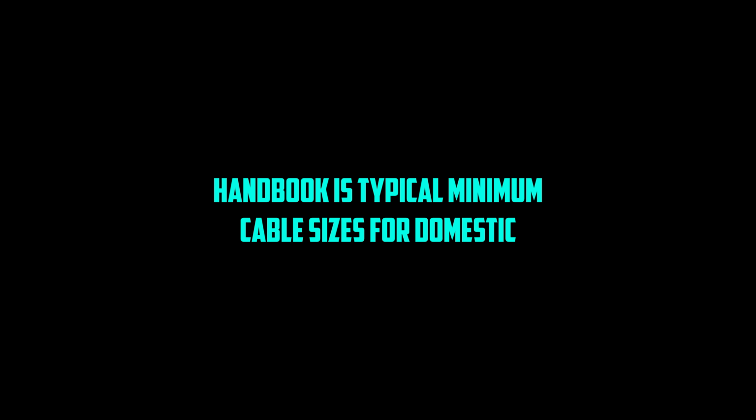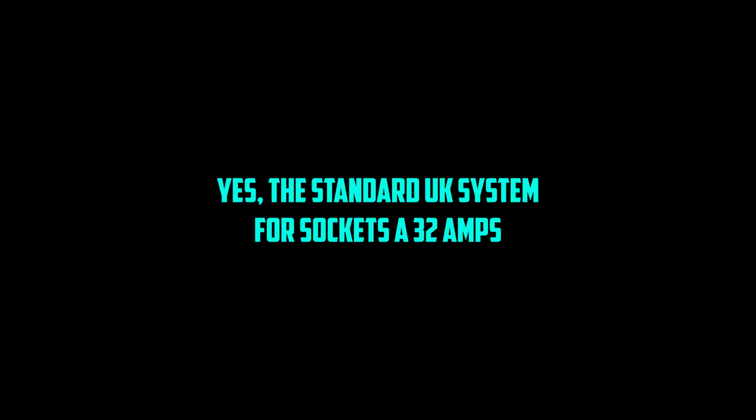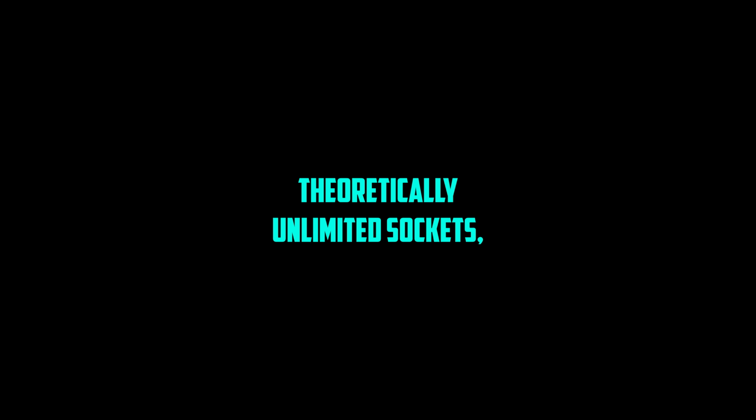Cable sizing must be calculated carefully. Essential to prevent overheating, based on the maximum current expected and allowable voltage drop. The handbook gives typical minimum cable sizes for domestic circuits. Ring mains for sockets are typical. Yes, the standard UK system for sockets. A 32 amp circuit loops around the area, connecting sockets in a ring. Theoretically unlimited sockets, but regs limit the floor area per ring, 100 square meters.